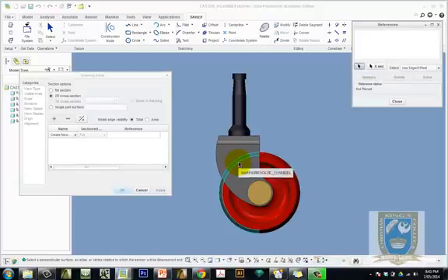That's fine. At this point, I'm trying to get some references on the model to allow me to draw a line through the center of this axle. I'm then going to follow this edge here and then go through the center of this axle here as well. With my references tab open, I'm just going to select a cylindrical surface there.